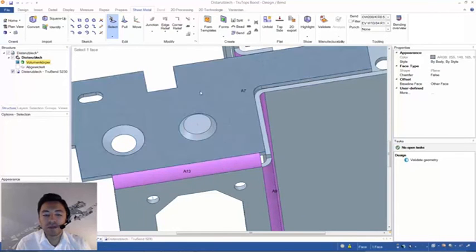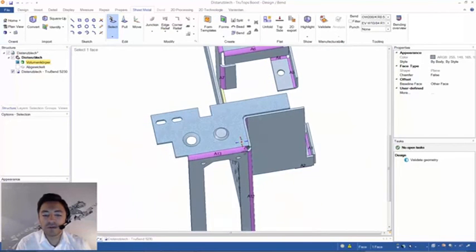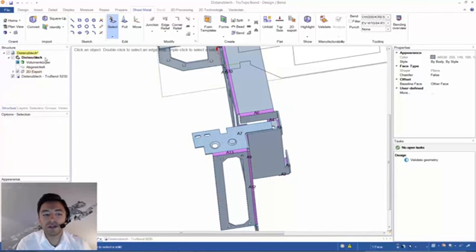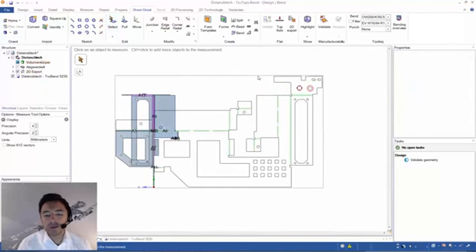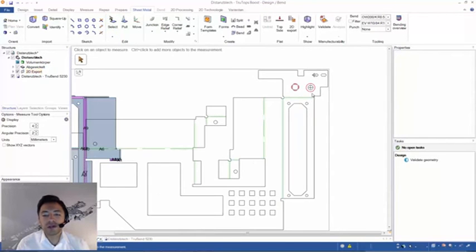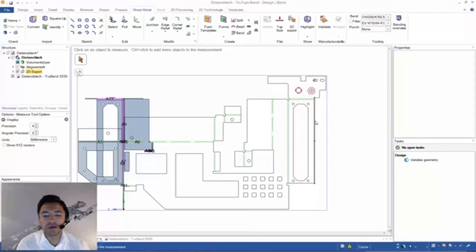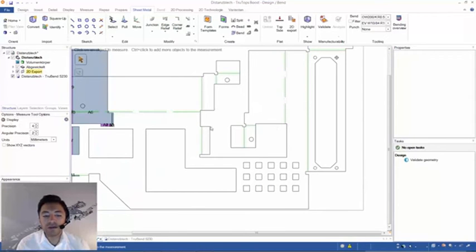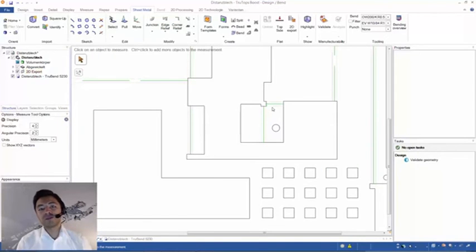All right, that special feature of exporting 2D geometries, which I have mentioned before, is right here. So if you flat out, you see within the structure tree, the 2D export is inserted. And basically we see within the 2D export what is being marked and what's not being marked. And so the lines are just deactivated, the layout lines. Otherwise, that 2D export will be the base for your laser program.